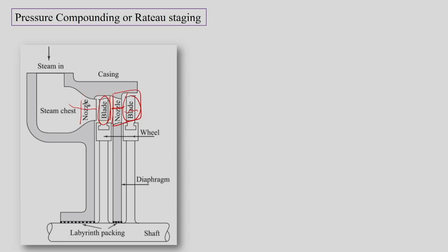Here we are calling it pressure compounding, since not the complete enthalpy drop or pressure drop will take place in one nozzle, but we will have multiple nozzles in the stack.